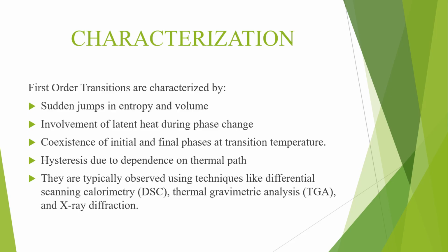So the characterization of the first order transition is given by a sudden jump in the entropy and volume, involvement of the latent heat during the phase change, coexistence of initial and final phases at transition temperature, hysteresis due to the dependence on the thermal path, and they are typically observed using techniques like differential scanning calorimetry, thermal gravimetric analysis,